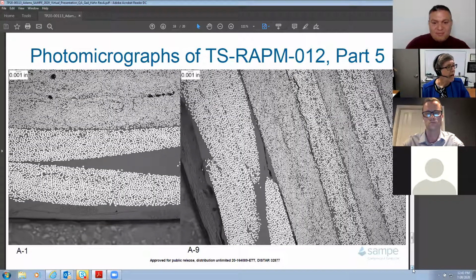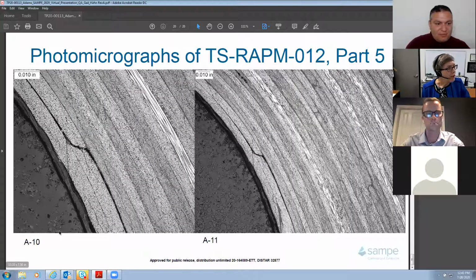Limited porosity. Again, we do have a little bit of a crack perhaps here at the interface to the cloth. And we did find this one area, in section A, outside of the main part, with some cracking, but overall very, very good quality. This saved us a great deal of time. In the paper we discussed that we did a hand layup version as well, and with that we're talking 3 shifts. When we're doing compression molding, it is much faster and also, we believe, more reliable for quality.